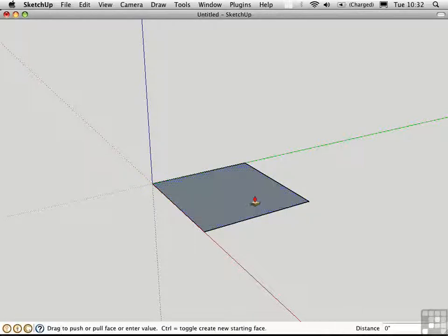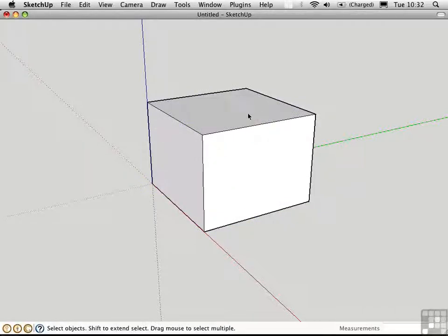We're trying to model the form, which we can scale later. Push-pull this rectangle up, forming a box. Draw an arc on one of the faces from some arbitrary point along the vertical edge to a point that's equidistant from the corner, as indicated by this magenta inference. Make the arc tangent to the edge, and then type in 6s, return,